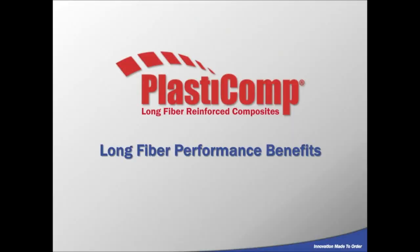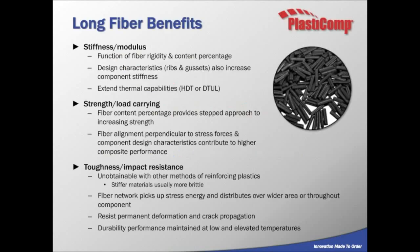So what are some of the benefits of long fiber thermoplastics? Stiffness and modulus. This is a function of fiber rigidity and content percentage. So if we're using carbon fiber, it's going to be stiffer and stronger than glass, just as an example. Also, design characteristics, which Mark Henry will go over later in the presentation, can be used to improve stiffness. And then we have extended thermal capabilities, such as HDT, with our fiber reinforced materials.